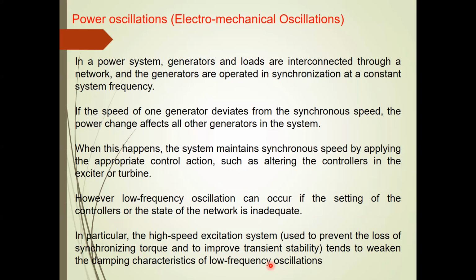Yes, you're right. Synchronous generators introduce inertia in the system. But if you install PV systems, the inverter-based renewable resources, they don't have any inertia. You add power from the renewable resources, but you don't add inertia, and thus you don't introduce sufficient damping torque, or damping characteristic, and that could also be another reason for the existence of low frequency power oscillation.